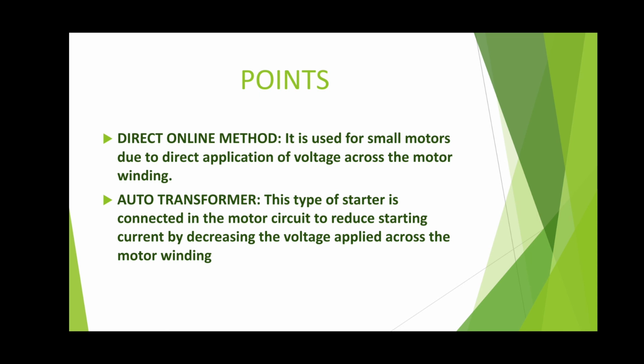When the start button of the direct online starter is pushed, the coil is energized, causing 4 sets of contacts to close. 3 contacts supply 3 phases to the motor, while the 4th one shuts out the start button. Remote control is also used when a stop button is connected in series with the coil.